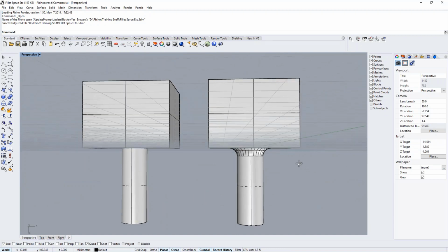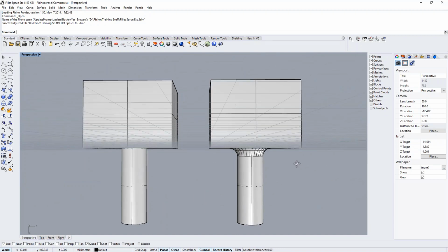And while it is possible to cast resins, it is somewhat challenging. There's a little bit of a learning curve. But something I've discovered, I see on the forums a lot of people talking about problems they're having at sprue junctures and just voids in their casting. And I think a lot of the problems that people are attributing to resins are a lot of times engineering problems. Because when we're carving waxes, I think we sort of just automatically practice decent engineering because it's pretty hard to carve a perfectly sharp angle.